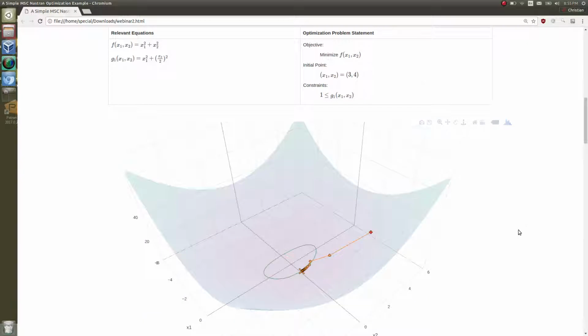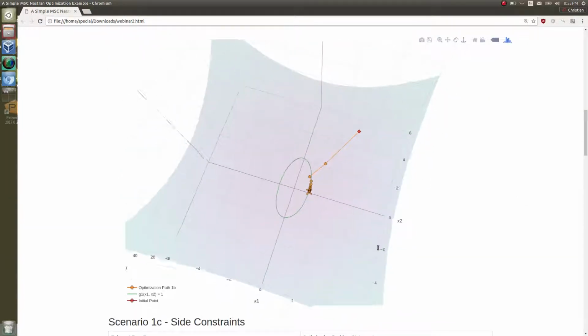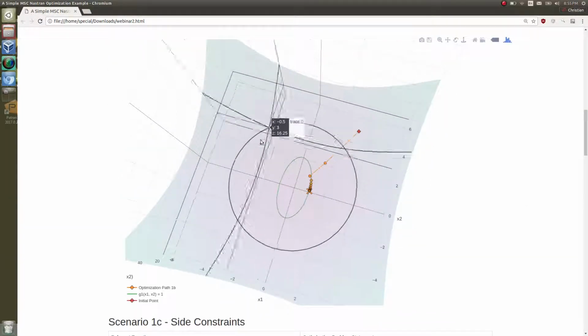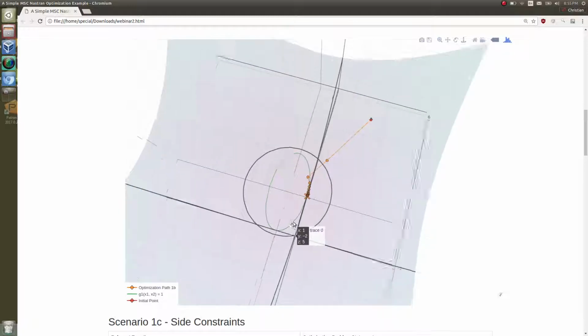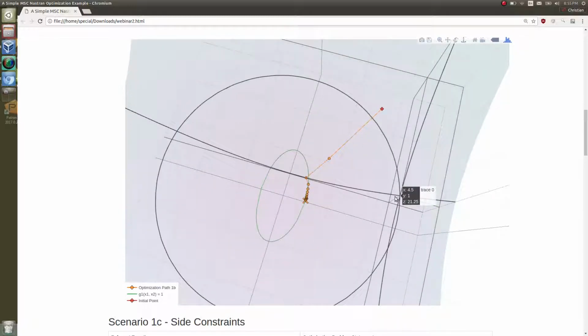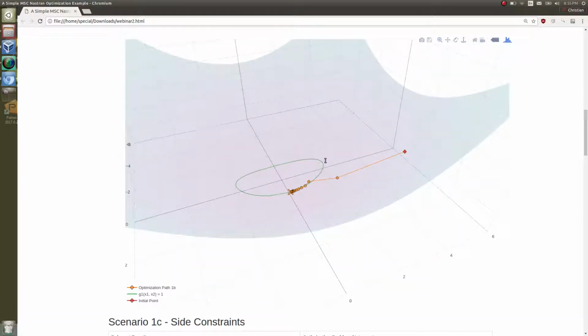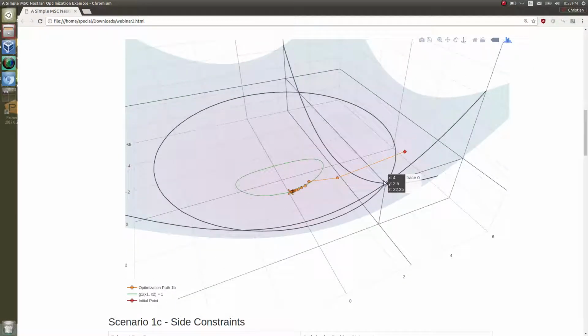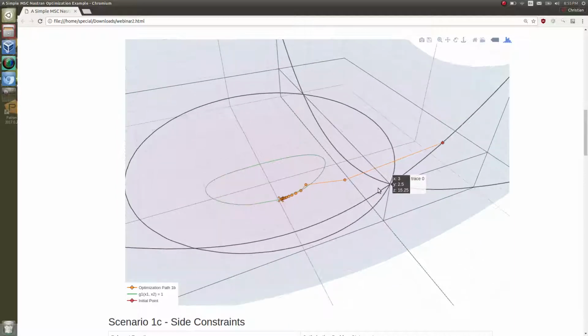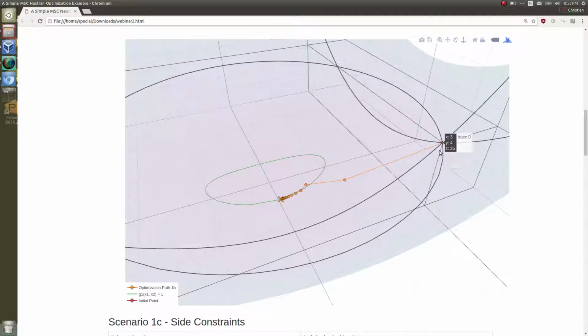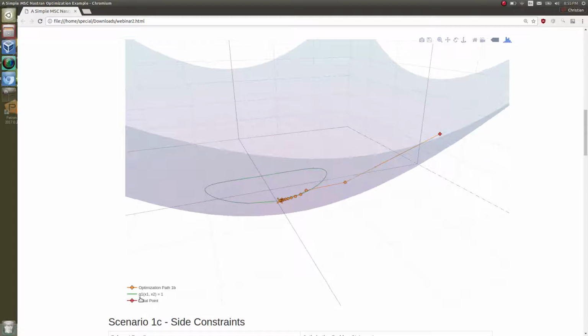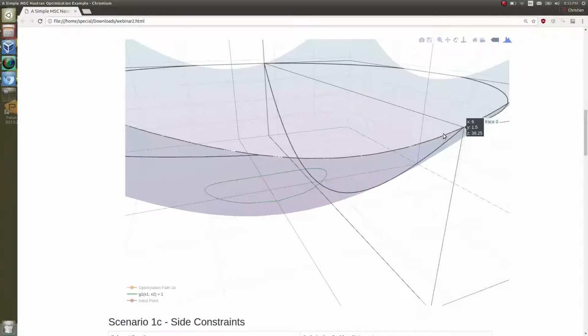So basically, if we look at the graph here, any value for x1 and x2 outside of this green ellipsoid is an acceptable design or configuration for the objective. Now here, let's explore what Nastran, or the optimizer in Nastran, will do. It will start off at this initial point like before. Here, let me go ahead and show you the initial point here in red.